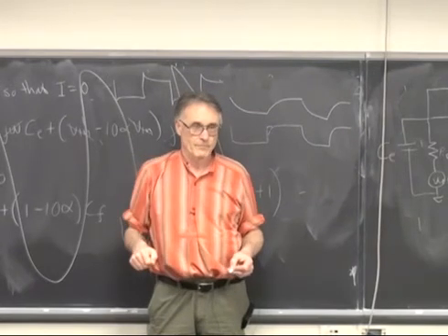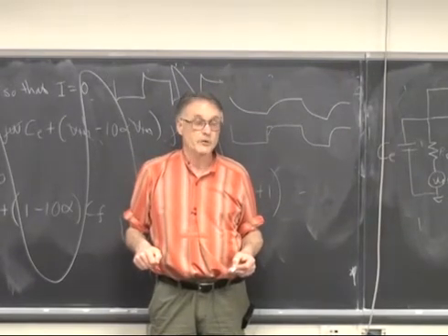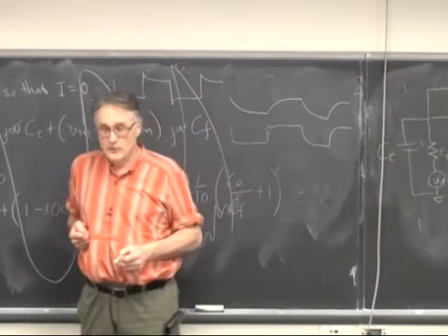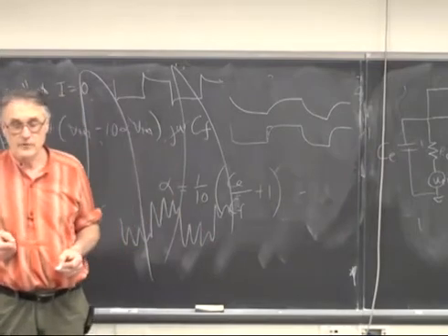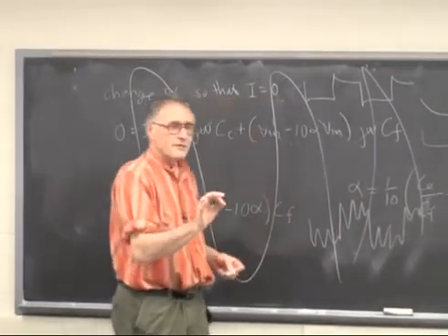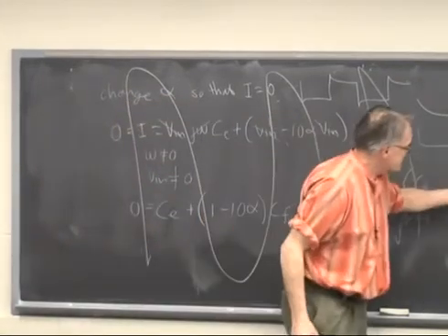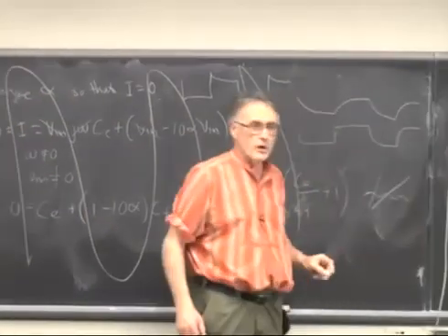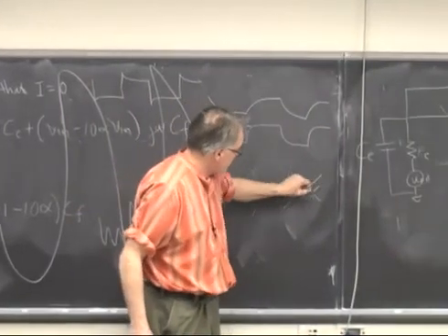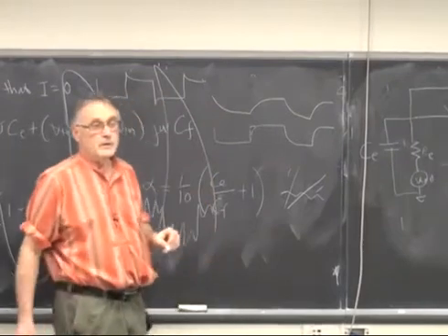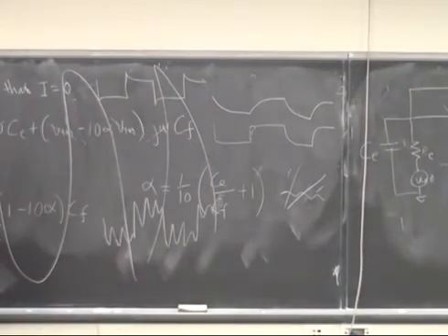Why not use the shielding trick instead? You use both. So you shield first. You use a driven shield first. You can get rid of almost all of the capacitance that way, except down near the tip of the microelectrode, which is underwater, which you can't drive. But for that, you can use negative capacitance feedback. You can negative capacitance cancel.